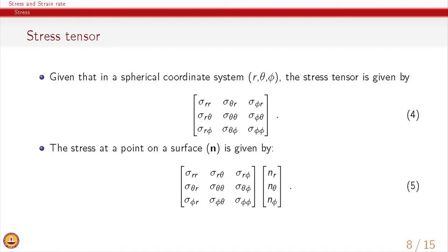And as a preliminary observation, we will see that cone and plate device is where shear flow is observed. So, since theta and phi are the dominant components, one of them being velocity direction, the other one being direction of the shear, we will see that sigma theta phi or sigma phi theta will be the two dominant components which will be discussed. In fact, we will see the presence or absence of normal stresses, as we saw in the unusual flow phenomena lecture where we also discussed rod climbing and other such effects related to the normal stresses.